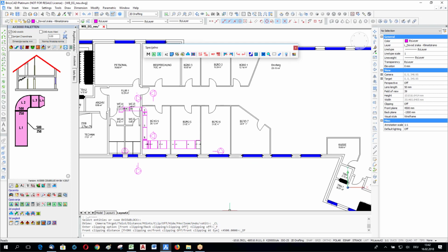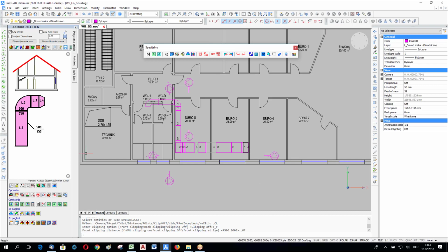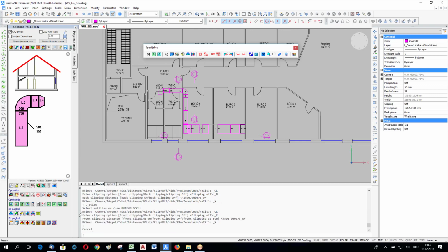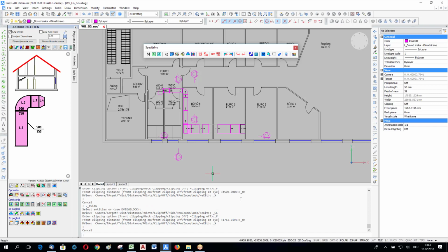There we have to check, there's a wrong command inside. They are missing 2 lines in the group. There we have to check the software is missing 2 coordinates because the point of view has to be designed first. You're looking from 0, 0, 0, what is up as a reference height. Otherwise, depending on this, it's a little bit moved and the coordinates are not correct. But you have to define the upper and the lower level, and everything above or below those 2 coordinates will be switched off.